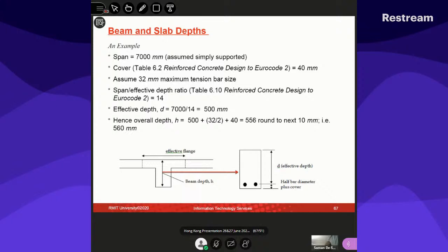Otherwise, you can also use line diagrams in a 2D analysis, either using Space Gass. If it is indeterminate, you need a software program to calculate and give you the moments, M star, and shear forces, because it is not determinate.